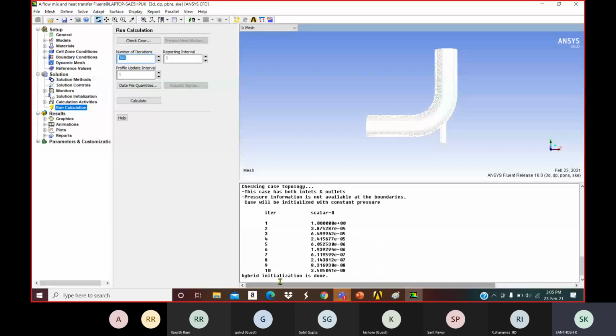No, sir, if it's not getting converged, might be again we have to go with 200 iterations. If you want exact calculations, then you have to keep on increasing iterations. No, sir, I cannot say how many iterations you have to use. You cannot ask me that question because it might take more than 300 or less than 300. It does not depend upon us. If I give 300, it might be solved around 50 to 60 iterations also. Until it gets a constant value, the solution gets converged. If it is not getting converged, then you have to increase 200 iterations. I hope you understood this.